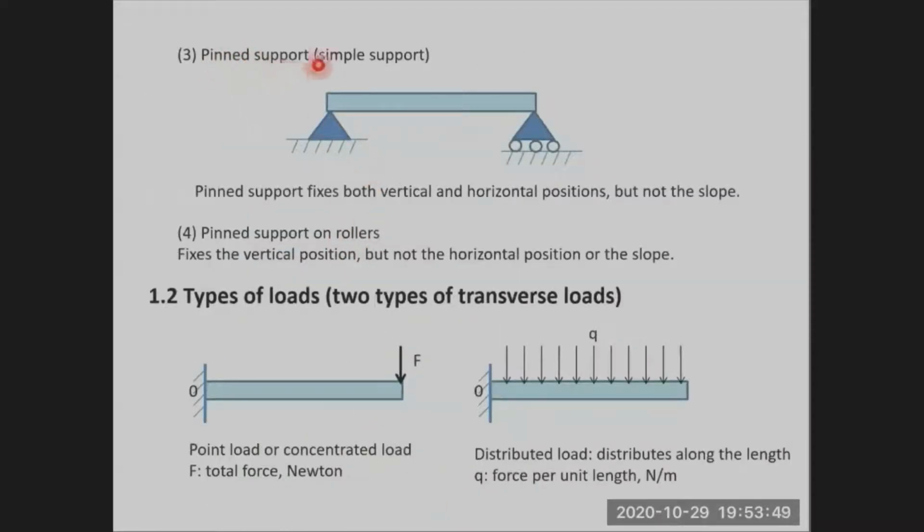Pinned support or simple support. The support shown in this figure is a pinned support or simple support. Note that a pinned support fixes both vertical and horizontal positions. It fixes position, but not the slope, so this beam is still able to rotate around this support.